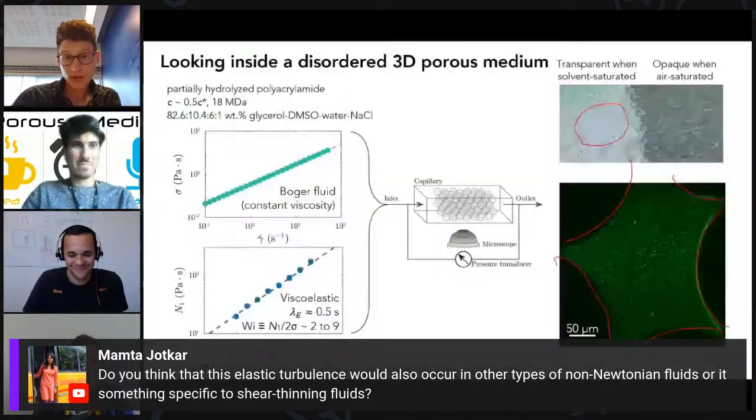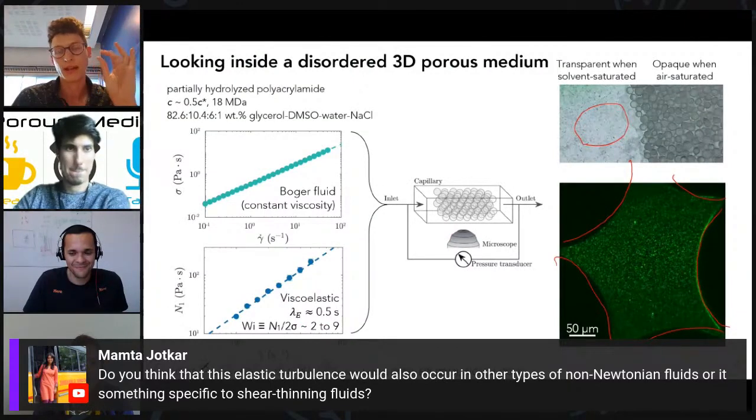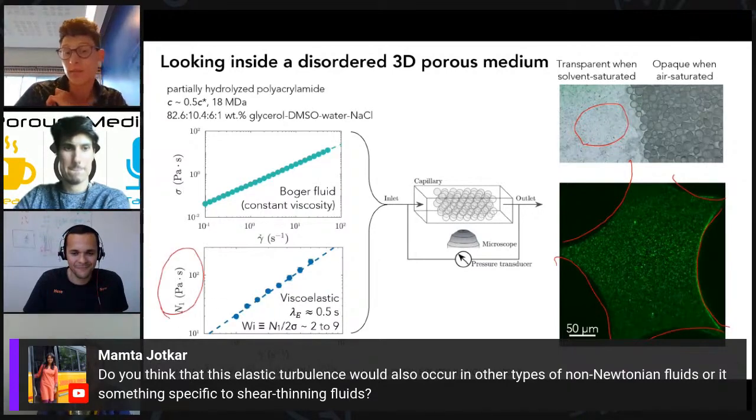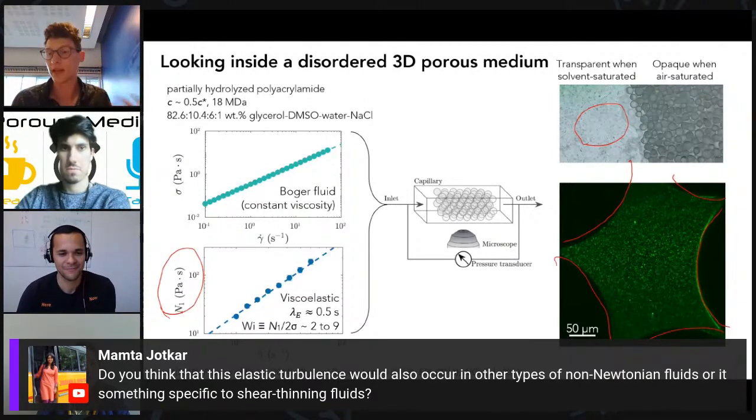So here I'll just remind you, though, we don't have a shear thinning fluid. We have a Boger fluid. So I guess it has a very light shear thinning. The shear thinning exponent is 0.93. So I don't think that's really important. I think what matters is that you have an elastic fluid. So I think shear thinning is potentially fine. It's something that we certainly want to explore, and we're playing with solvent conditions, and it seems to matter. That's an ongoing project, but the shear thinning definitely matters and adjusts what this resistance looks like, but you still get similar flow behaviors and similar increases in resistance.